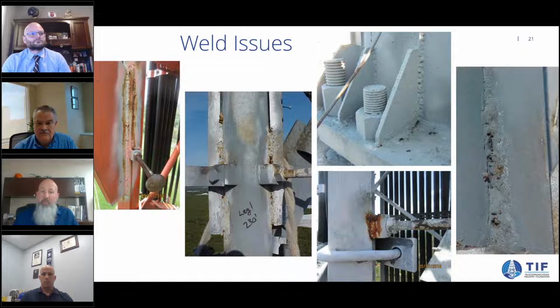Now, John, from a structure owner's point of view, what are your thoughts when you see welds like this on structural modifications? I mean, this is why we have CWI requirements, right? It provides that extra layer and that expertise on the weld itself. And that also goes to repairing welds as well. As a tower owner, we send crews out, take as many pictures as you can, and we'll get that information back. An engineer will specify a fix. But you know what? That engineer is not out in the field.